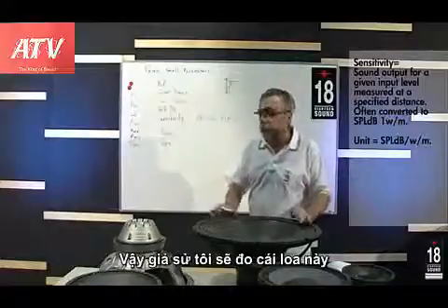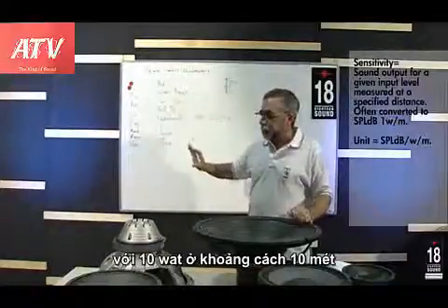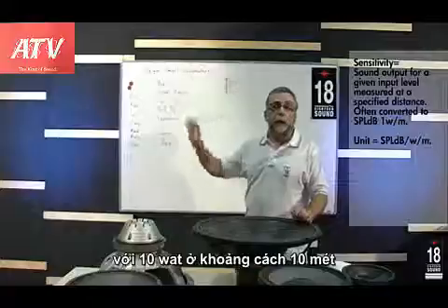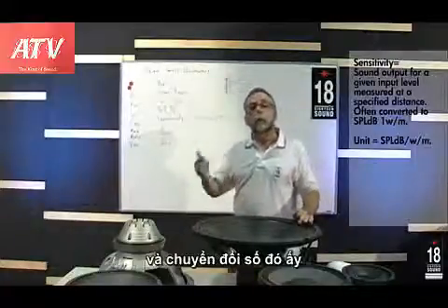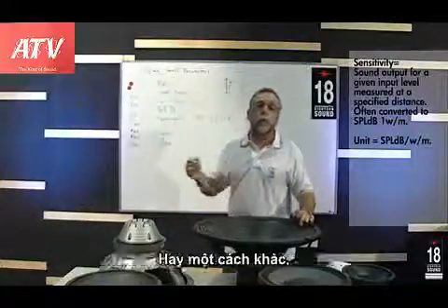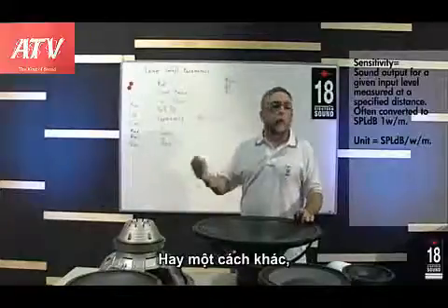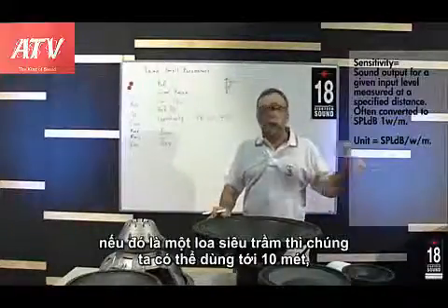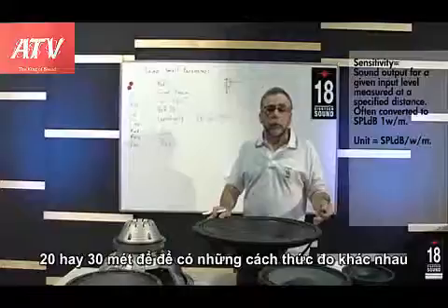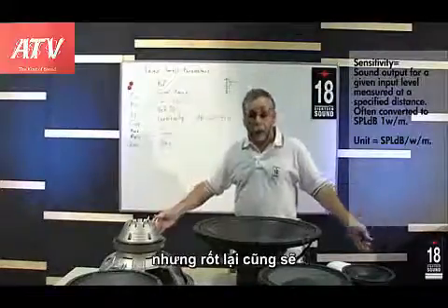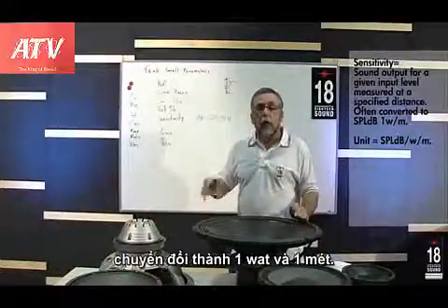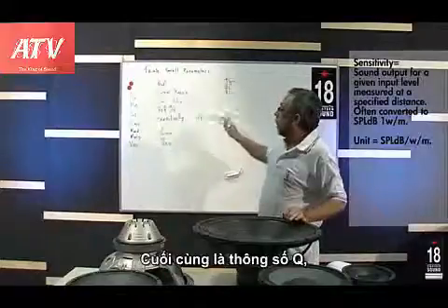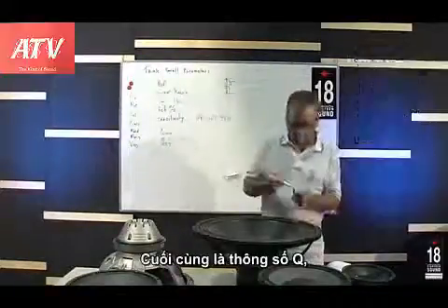So, hypothetically, I'll measure one loudspeaker with 10 watts at 10 meters and convert that to what sound pressure would be with 1 watt and 1 meter. Or another one, if it's a subwoofer, we might go to 10 meters or 20 meters or 30 meters in order to have a very different kind of measurement. But again, we'll convert it back to 1 watt at 1 meter.